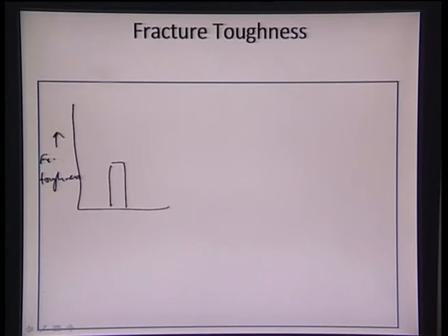If we take the fracture toughness of only hydroxyapatite, it will show a certain value, and with the addition of CNT, it goes to approximately double. So we had hydroxyapatite plus some CNT, approximately 4 to 4.8% carbon nanotube. It will approximately double the fracture toughness.